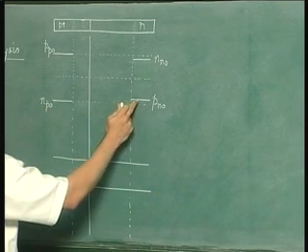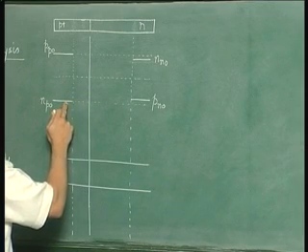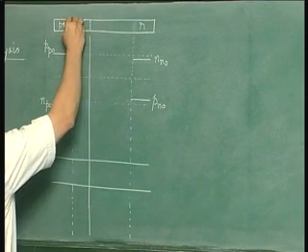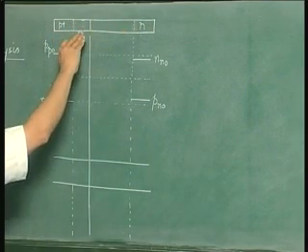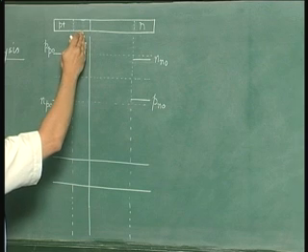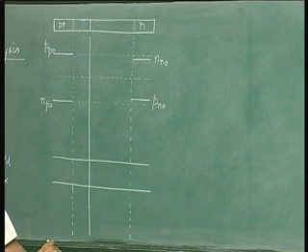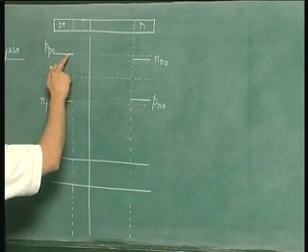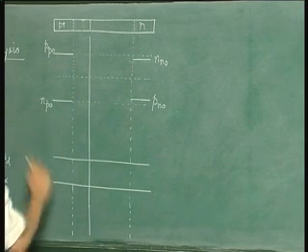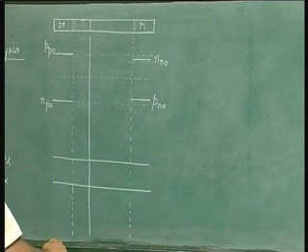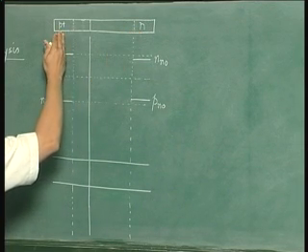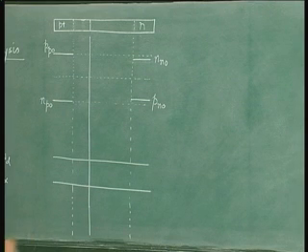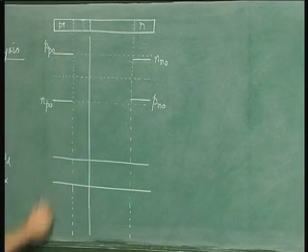Notice that these concentrations correspond to the regions which are far away from the junction. This is because we expect some variation in the concentration around the junction. Because the doping is changing abruptly, the concentrations of holes and electrons have to change. So far away from the junction, however, the conditions in the regions are the same which would have been if these two regions were isolated, that is if the junction was not present.